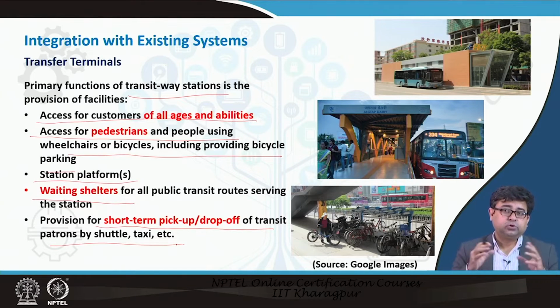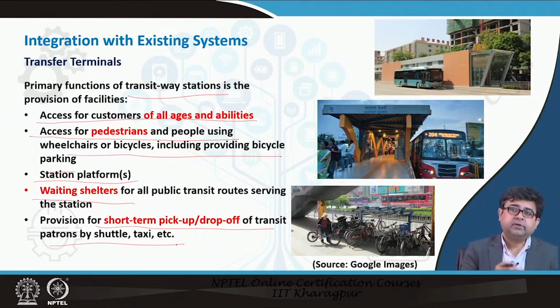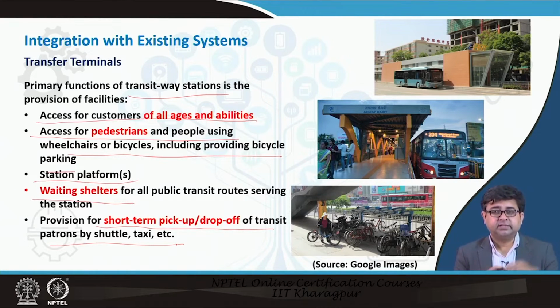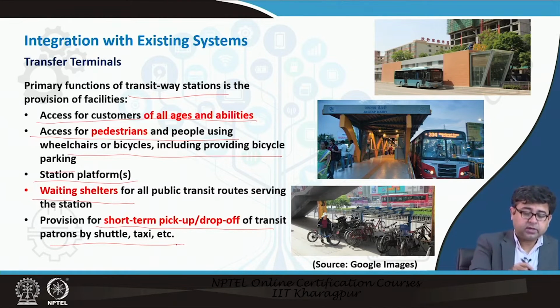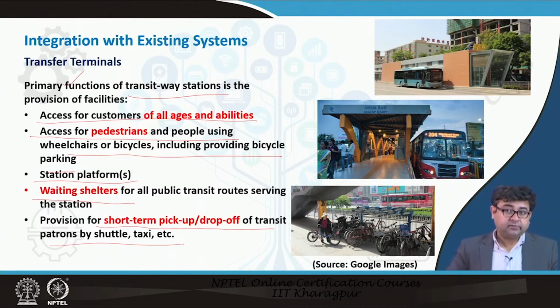Such stations should have at least a circulation pattern for pick-up and drop-off, or 10-minute parking where people can wait as the bus or train is arriving, to pick up and drop off their child, friend, spouse or whoever it is. That type of facility should also be thought of, because that is one of the primary functions of any station.